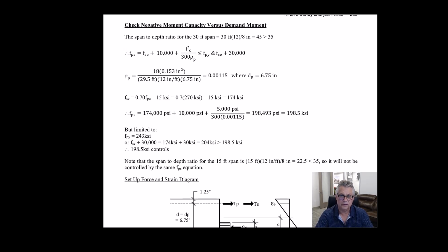I love to ask the designer, what's happening here? Why are you only showing bonded reinforcement requirement in your calculations from the midpoint of the column to one side of it and not the other side? And so far, nobody has ever had an answer for me. I know the answer, and now you know the answer. But anyway, we'll keep that our secret.